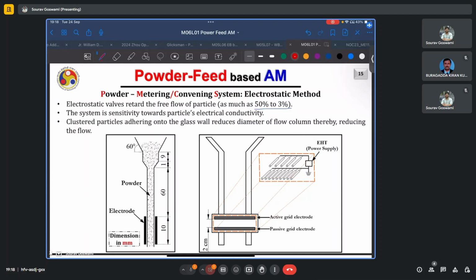And under the action of these electrostatic electrodes, there might be an accumulation of agglomerated powder inside the funnel or inside the channel, and with time, this might increase to narrow down this passage, thereby limiting the amount of powder which can pass through.